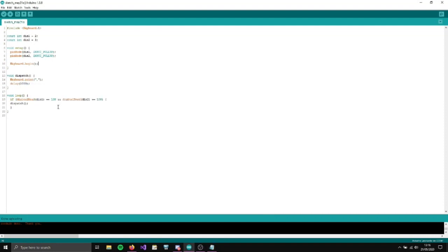Okay, so next up I'm going to show you how to write in logic for maybe a switch or a button. So the difficulty with many buttons is that they don't come latching. Like I've got a yellow button here, which I can use for restraints. And so the restraints button there, which I've programmed in, I believe, hopefully this is right, I've got it as pin 5.